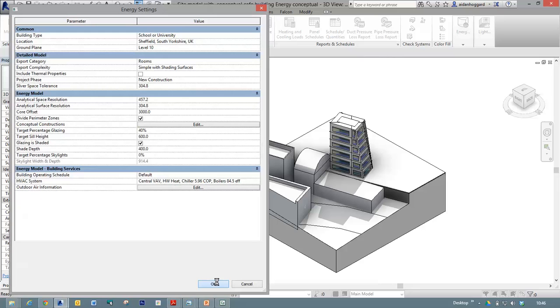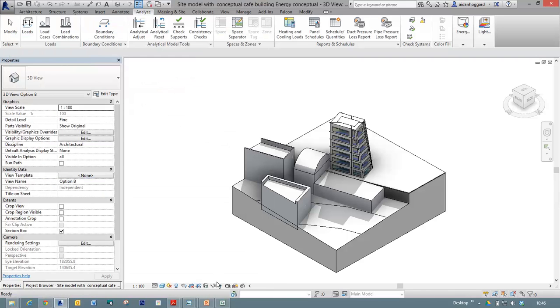So, this is quite a small building we've got. If you're doing a bigger building, if you took this room, for example, we've got about 6 meters would be our core offset. So you can just set that. What it allows you to do, even at this basic level, is if you've got a whole range of spaces in the core that won't need the same level of heating, you can just make that bigger or smaller.